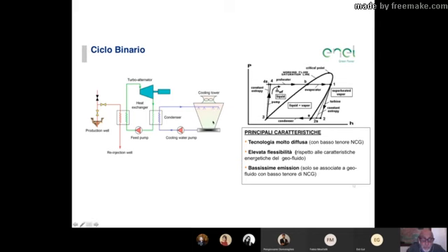Now again, regarding the cooling tower, if you're in the tropics, you have a lot of water, you might have a river, so you can use a very efficient cooling tower, run on evaporating water. But you need to use fresh water, usually from a river or from a lake. And this water is going to be evaporated in the atmosphere, so you're going to lose the water. And this means I can use this only wherever you have a lot of water at low cost.